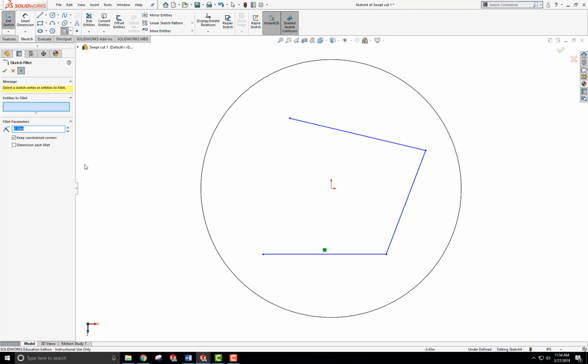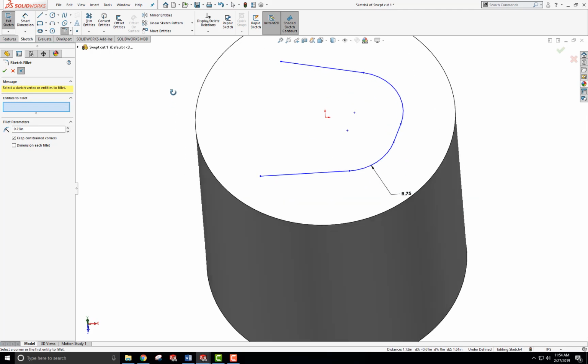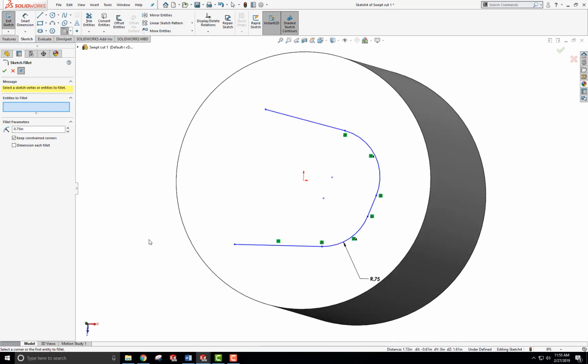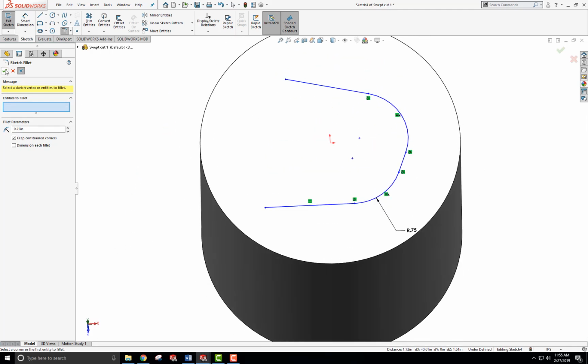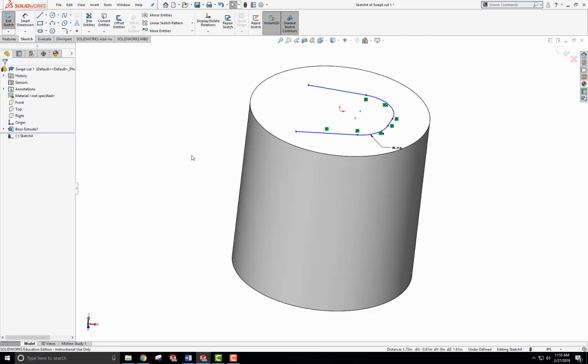And you want to have a curve for this to go around. So a swept cut can't follow a rough curve like this. It'll make it very rough. May have problems with that, but you want to make radiuses with tangencies for it to follow the path. Okay. So again, this is a swept cut. I'm cutting to the top surface, so I'm going to create a profile now.